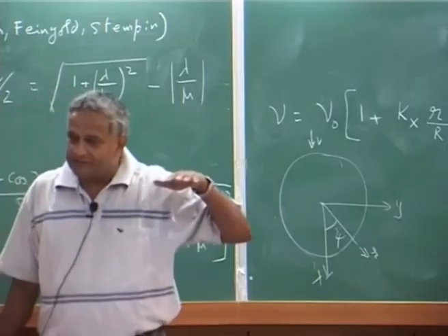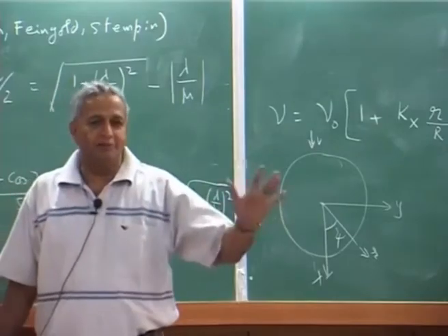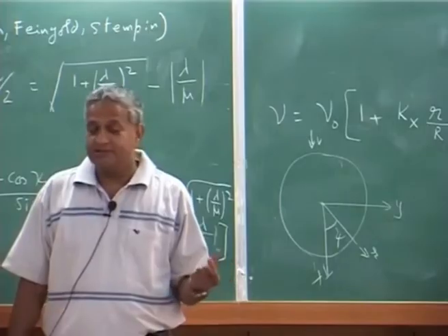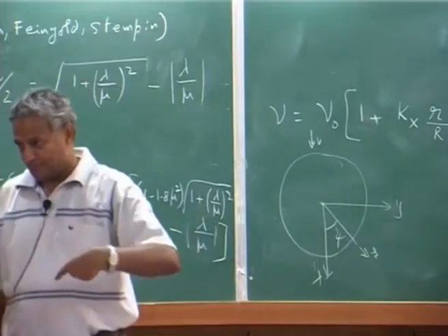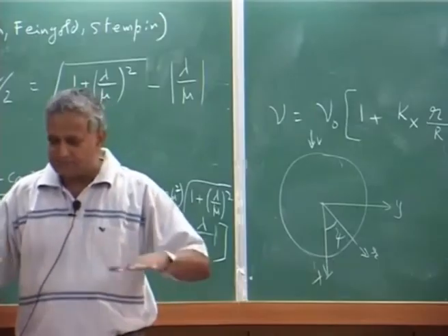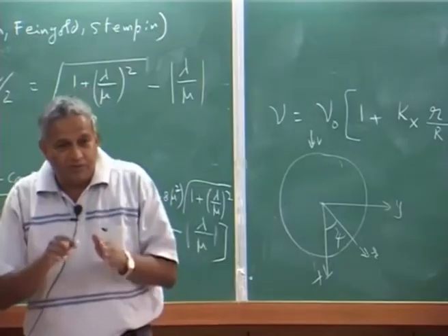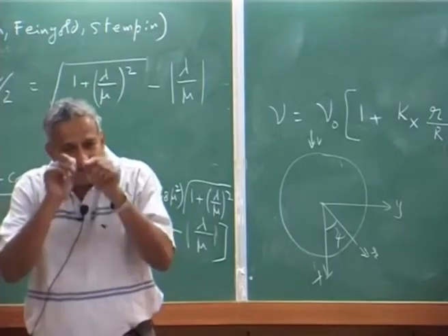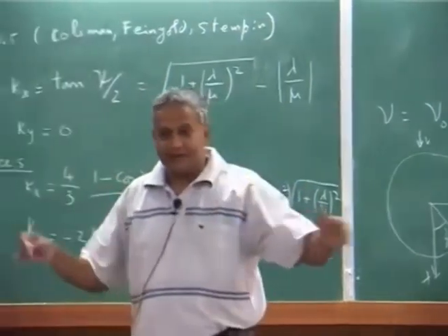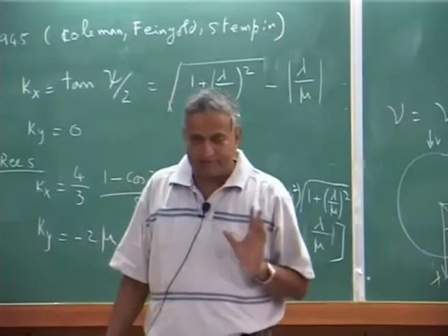But even the first part, which is called level flight, it is called a trim or equilibrium. But the trim equilibrium part itself is an aeroelastic problem. Then you will slowly realize in forward flight things become much more complicated, and then you start analyzing only some narrow portion for a specific case. It's not that you include everything in your analysis. Okay, this is what happens.